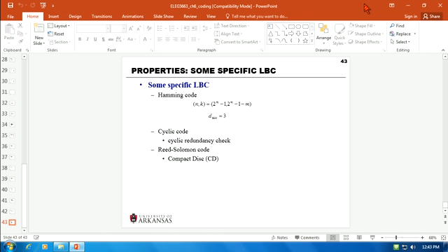And actually, he did achieve that limit, but he was using an ideal channel code. In the proof of his theory, he assumes that the block length of the channel code is infinity. Once it goes to infinity, he can prove that this is the best we can do. But in practice, we cannot use a channel code with length n being infinity. We have to have a finite code length.